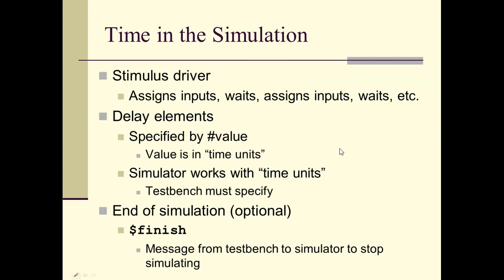Time in the simulation is handled by the stimulus driver, and generally what it does is it assigns some inputs, it waits, it assigns some inputs, it waits, etc. So there's a way to specify delay elements, essentially just a pound sign with a value. It defines time units.